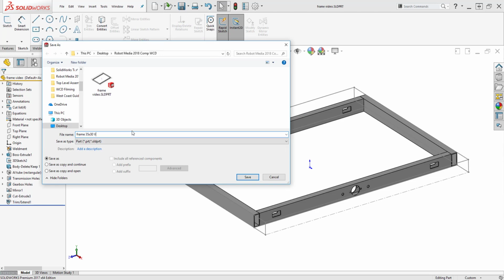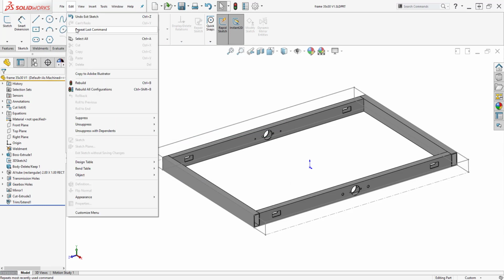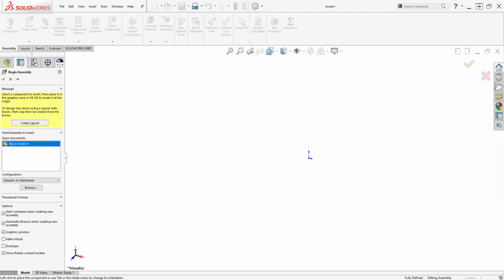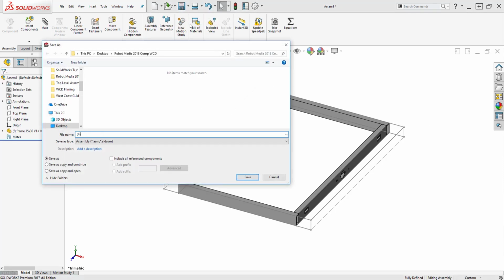Go ahead and download the gearboxes you selected in Part 2 and save them as a part file so that the file is easy to manage and no parts fly around on you. If you've never created a West Coast drive, you should not be modifying your gearboxes, so this simplification of the part files will help you with your assembly process.